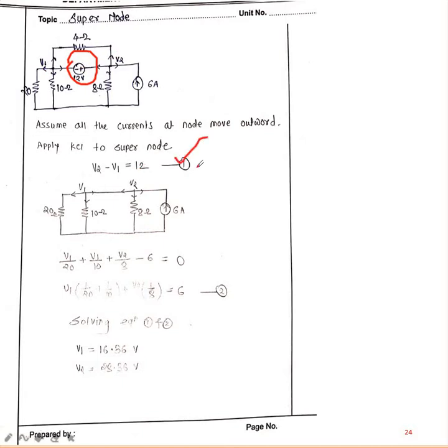So first, the equation is ready. Then remove this voltage source and make it a closed circuit. Once it is a closed circuit, the 1000 here is of no use, leave it. Shorted, that's all. Then as usual, apply node analysis, Kirchhoff's current law plus Ohm's law, with V1 and V2 values, and write only one equation. That's all. Equation 2 you can get. Solve it, then get V1.